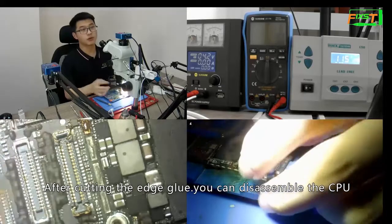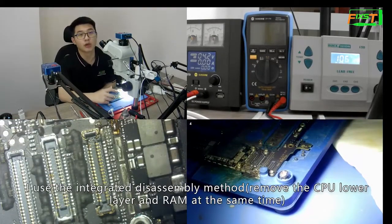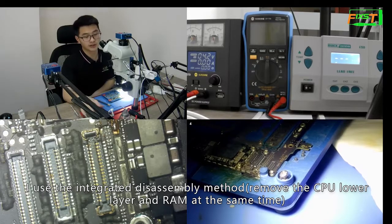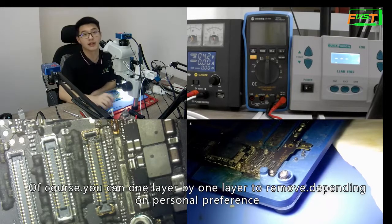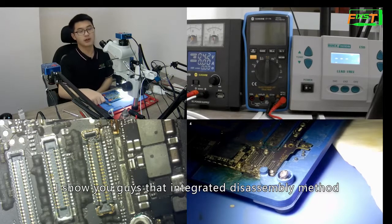After cutting the edge glue, you can disassemble the CPU. I use the integrated disassembly method, removing the CPU lower layer and RAM at the same time. If you remove them one layer by one layer, it is easy to deform. Of course, you can remove them one layer at a time, depending on personal preference. I will show you the integrated disassembly method.